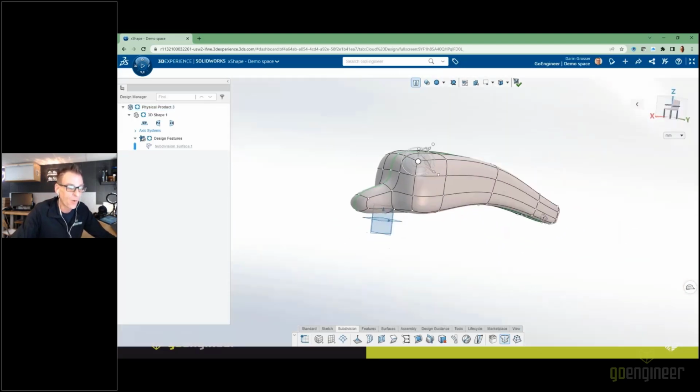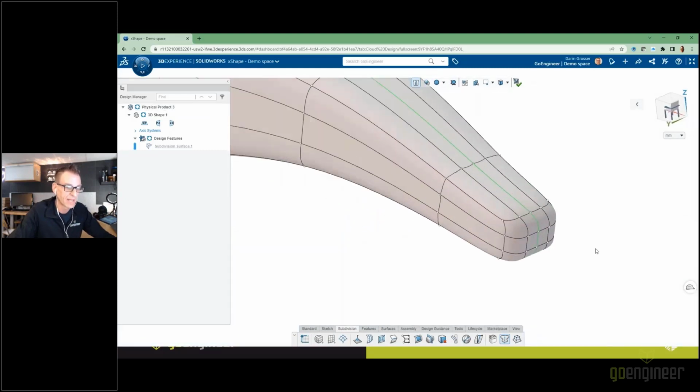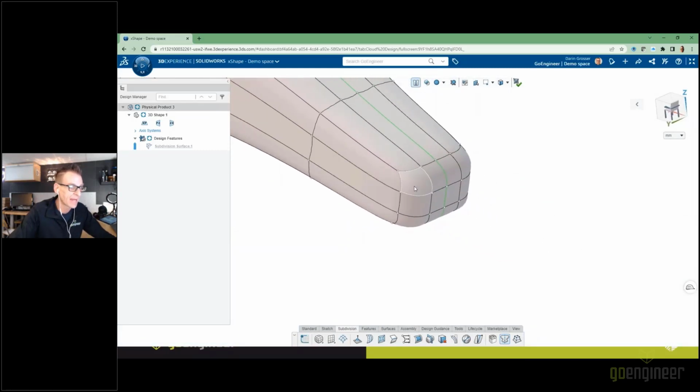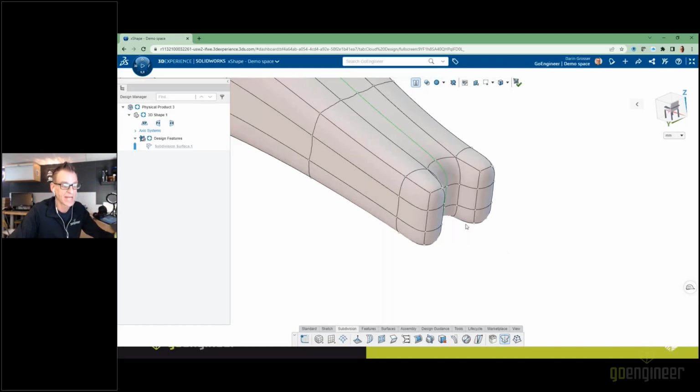Now, even so, if I want to come out here and add these tail pieces in the back, let's maybe grab 3 faces here. And quickly we'll use our quick toolbar to add the extrude this way. Now this is going to be no preview and symmetry is on. So watch what happens here. It's going to add it on one side and then bam, it's going to add it on the other.